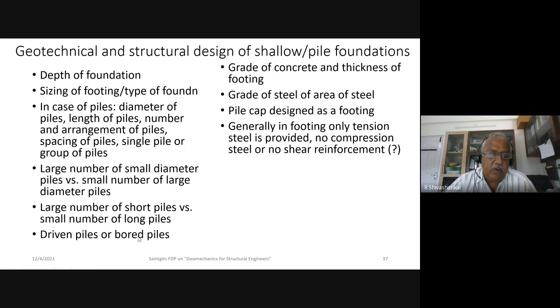You are also drilling a borehole, so there will be a lot of soil cuttings which will accumulate at the bottom. It is very difficult to clean. Practically, if you ask a piling engineer, it's very difficult to clean the bottom of a borehole even with high air pressure or water pressure.